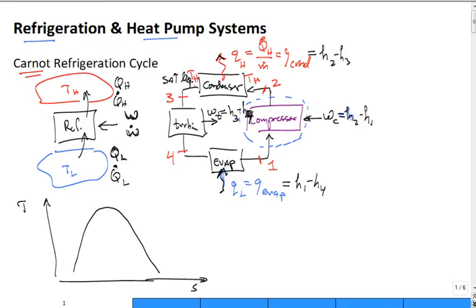So if we think about it, we have a high pressure side, which is the condenser side. If I just cut this in half, everything over here the pressure is high. And everything below, on the evaporator side, the pressure is low. So we'll talk about the condenser pressure. That's the same pressure at the input and the output. It's a high pressure. And we want that refrigerant to change phase at the same temperature.